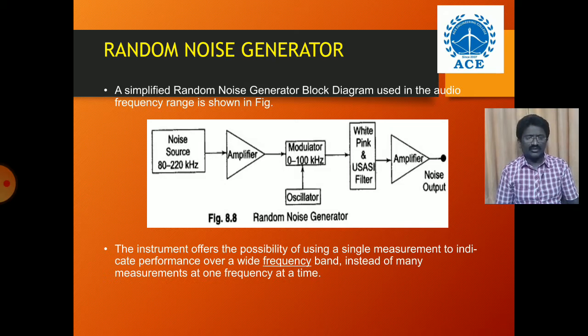Now by using the sine wave amplifier, Wien-Bridge oscillator, and square wave shaper, you can generate waveforms in the form of sine wave and square output. Actually here the Wien-Bridge oscillator generates a sine wave. With the help of the function switch, you can modify the output of the Wien-Bridge oscillator in the form of sine wave or square wave, according to our requirement.